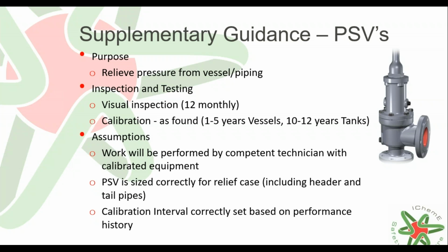Okay, now I'm going to talk about another case study, which is essentially what led on to the supplementary guide, which is all talking about PSVs. So again, look at what the purpose is. Obviously, they're there to relieve pressure for various cases, whether it's blow-by or fire case or whatever the size and case may be. And we also look at what our standard tools are for inspecting and looking after them.